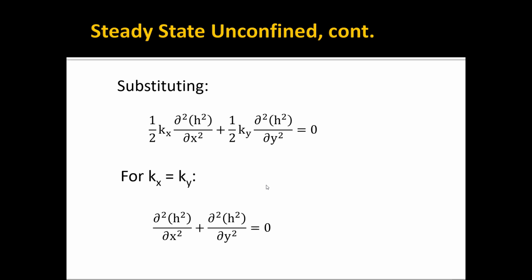And so why did we bring this up? We're going to be mainly dealing with the full three-dimensional term, but just in terms of completeness, if we're talking about governing equations for groundwater flow systems, you will sometimes see these forms. And in earlier versions of MODFLOW, based on the layer type in the grid, you would input transmissivity instead of K. But for this course, we are primarily going to use the three-dimensional terms that we came up with before, but I wanted you to be familiar with these other two special cases as well.